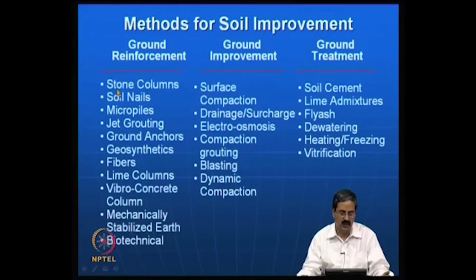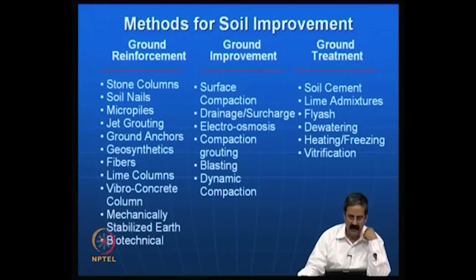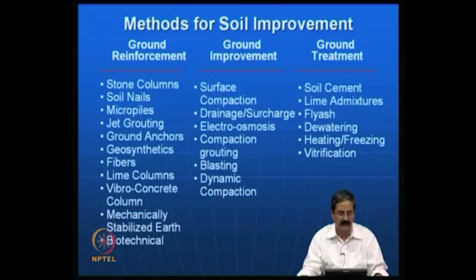Say, for example, stone columns is a technique used in the case of soft soils. In many of the coastal areas in India, whether it is Vizag port, Kandla port or Cochin port, you use stone columns. Normally you apply some load, and in the case of soft soil the load cannot be taken care of, but similar to piles, stone columns made of a matrix of stones and aggregates will take the load. So, it is a sort of reinforcing the ground, and that is the reason we call it reinforcement.